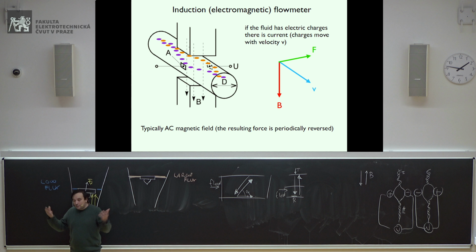And that is a very simple principle. Of course, if it's your wrong day and you don't have much luck, you might have some interference also at 1 kilohertz, and in that case, the principle doesn't apply. So that's why typically you select a frequency which is not a common frequency where you can find some other component of the noise. Definitely you don't select 50 Hertz, because you would sum your signal to anything which works at 50 Hertz, at least here. If you go to other countries, you have 60 Hertz. But this is a very important principle.